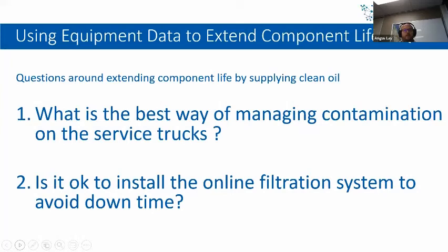The only thing to be aware of is that you are now potentially removing the evidence that you would normally detect through routine oil sampling of potential failures progressing or contamination issues. So once you put those systems on, you need to check those filters routinely at the services, cut them open, look at them, potentially get a filtergram performed by the lab if that's a service they provide, just to understand the contamination that's in there and whether it is an issue that you need to be managing.